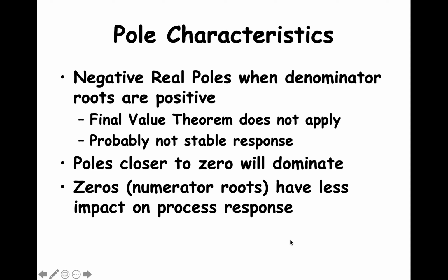We haven't said much about zeros. At this point, all we will say is that zeros are the numerator roots times minus 1. They have less impact than the poles on the transfer function response. They do have some impact, but less than the poles.